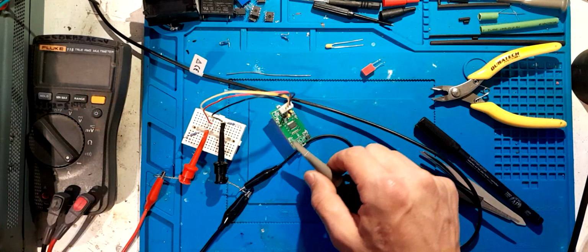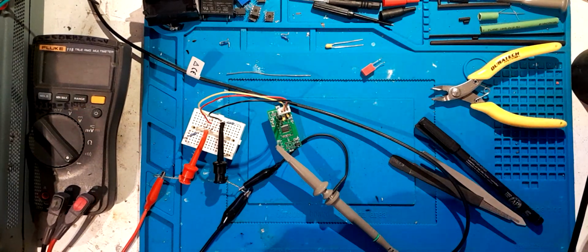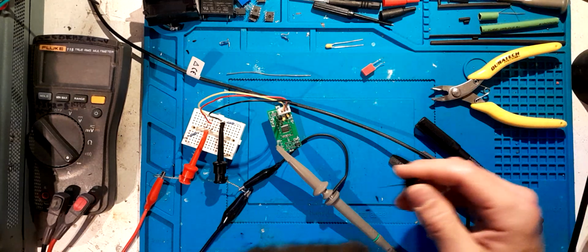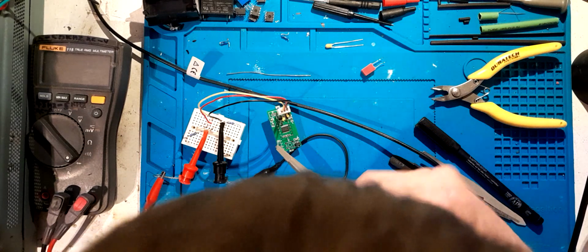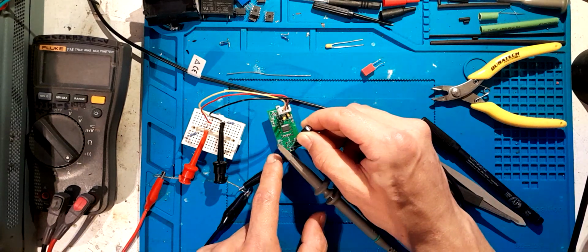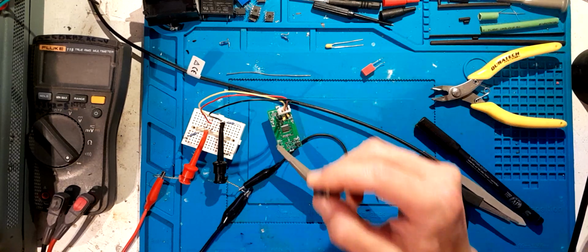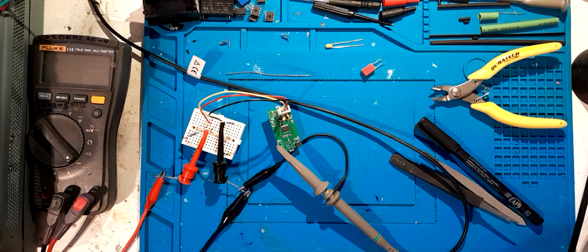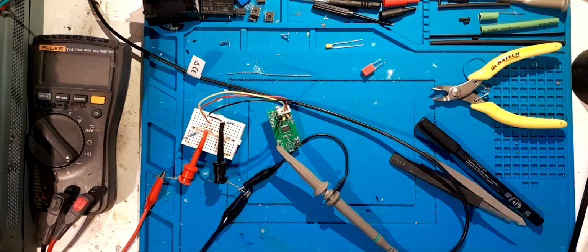Oh, I thought I just killed my regulator. Yes, I was going to swear. I thought I just killed my regulator. I didn't. I just pulled the power wire out of the board. Okay, the electrolytic, as I thought, its ESR rises way too much with frequency and it's just not even having an effect. So I'll put that back away.